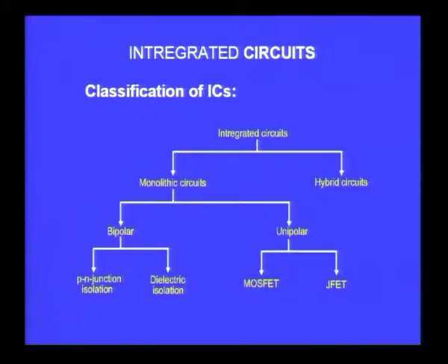Therefore, if I want to make an LC oscillator, I can integrate all the rest of the components onto the same silicon chip, and have the inductance alone as a separate discrete unit. Together with the silicon chip, they form whatever oscillator you wanted to design.